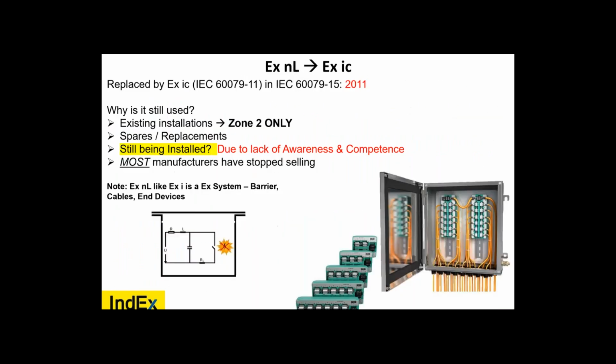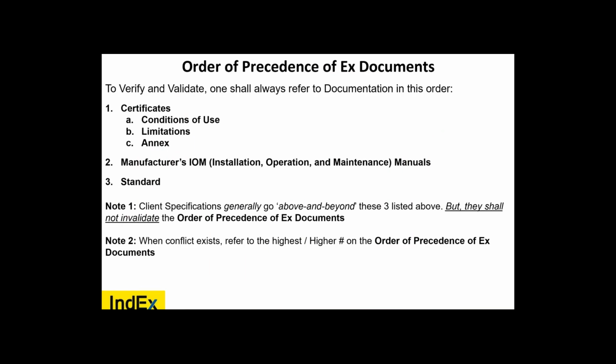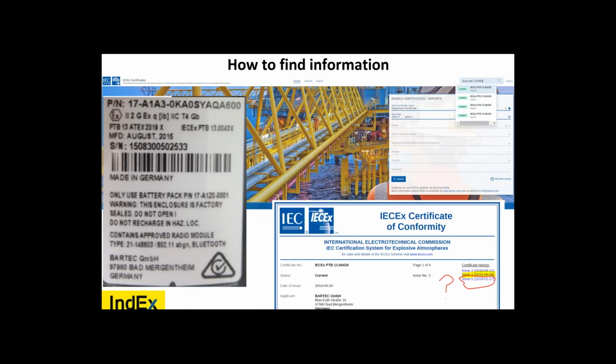all of us can look for certified people, equipment, and facilities on the IECEx website. So where do you go first? When you're inspecting a piece of equipment, make sure that your engineer gives you the IECEx certificate. If you have a device that has an ATEX and IECEx certificate, get both. I'll tell you, the IECEx certificate is much easier to read than an ATEX certificate.